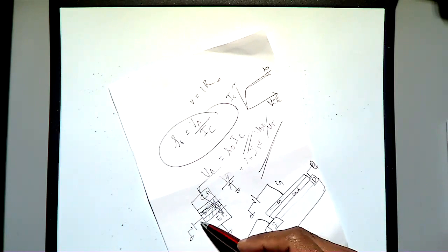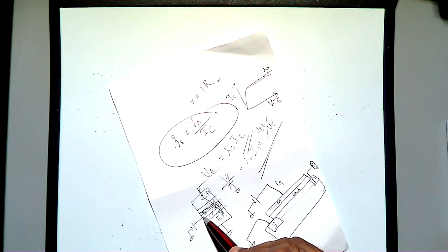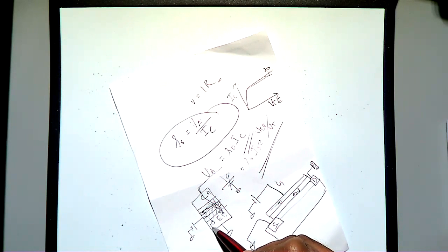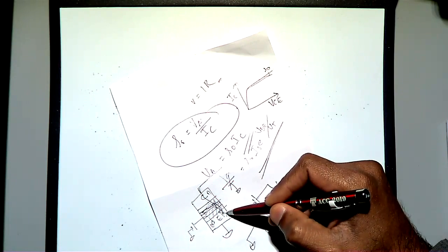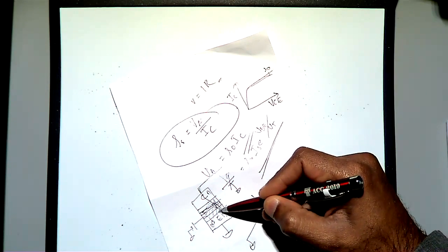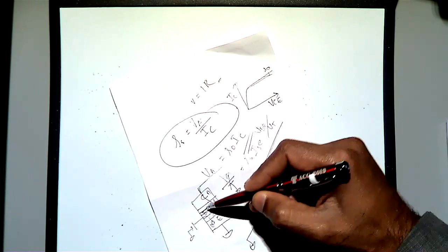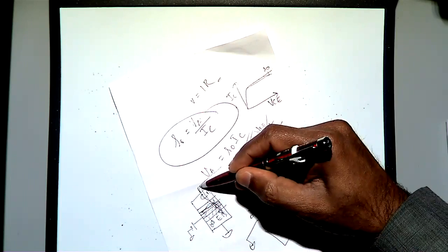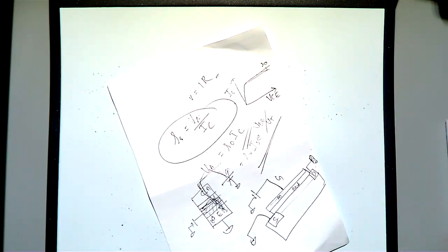In the BJT, you know that from here you get a voltage, then you are injecting maybe 10 holes into this region. Because this is heavily doped, maybe 1000 electrons come to this region, maybe 10 recombine with the P region, the remaining 900 seep through, and then you get amplification. Then you can write IC by IB, that is my gain. But somebody might ask, how will you explain the amplification, how the current is amplifying? Somebody will ask, okay, the BJT I know, this is where you can explain, but the MOS, how will you do it?